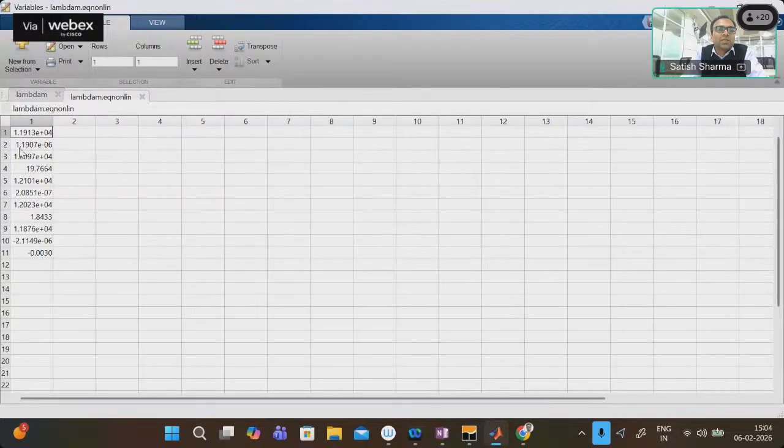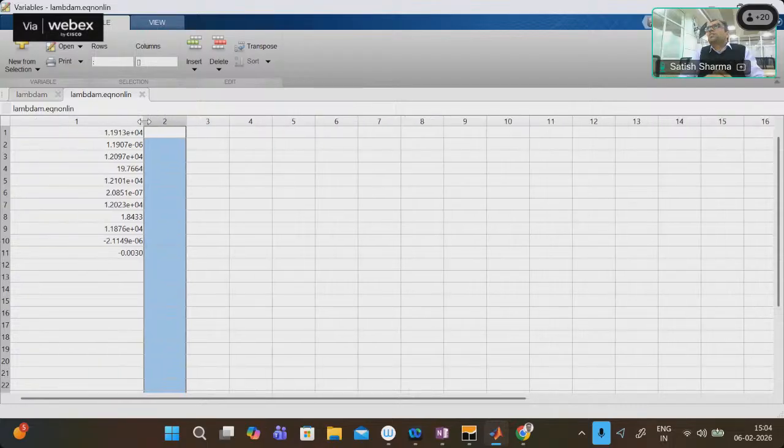So we have equality nonlinear constraints, and how many constraints did we have? Let's say if there is a 14 bus system, how many equality or nonlinear constraints will there be? For a 14 bus system there will be 28 equations: one for active power and another for reactive power. In this particular case we had a 5 node system, so that's why we have 10 nonlinear equality constraints. Though the delta reference equal to 0 is a linear equation, we have defined that as a nonlinear equation, as part of CEQ.